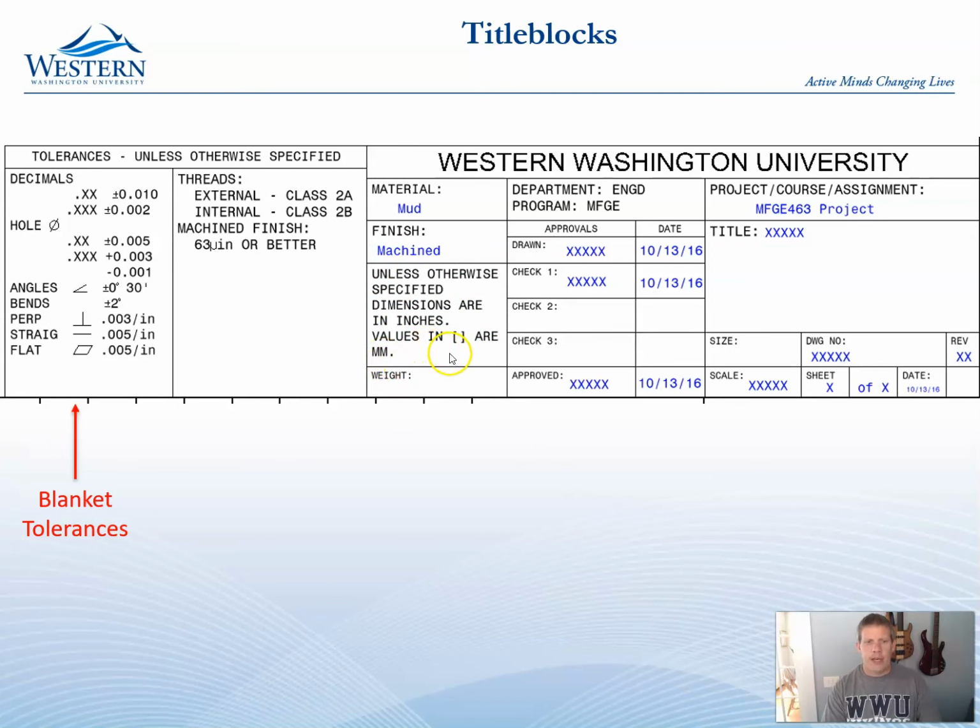If we have a project where things are in millimeters, then you need to change all these values, because 0.01 millimeters is tiny, and 0.002 millimeters is really tiny. So there are certainly machines, I worked with machines that can hit those kinds of tolerances, but does that apply to the current situation? Typically not. And you wouldn't ever also have something that is 0.003 millimeters per inch. So you would have to change all these values in the table to make sense.